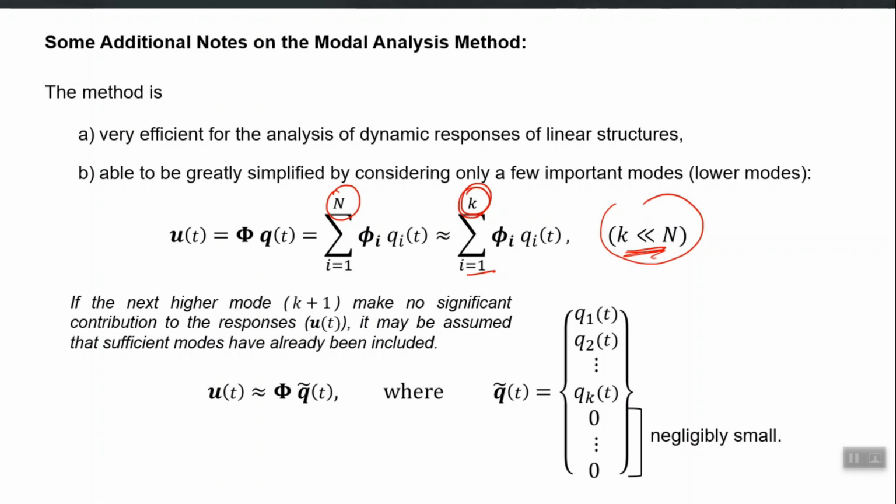But one more important thing is that modal RHA is a linear method. It is not a non-linear method. So if your computer model has the capability to simulate cracking, yielding and all those inelastic phenomena, then you cannot apply this method. Then direct integration is the only method available for non-linear dynamic analysis. But for linear dynamic analysis, you can either go for modal RHA or you can go for linear direct integration, right?